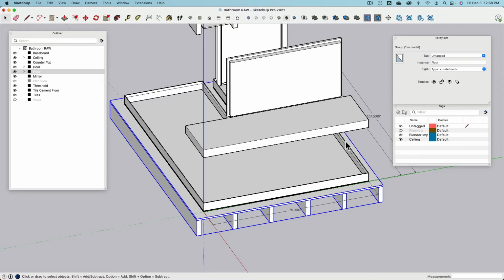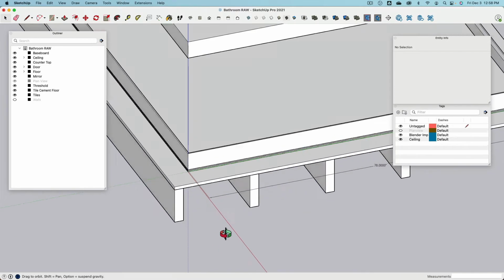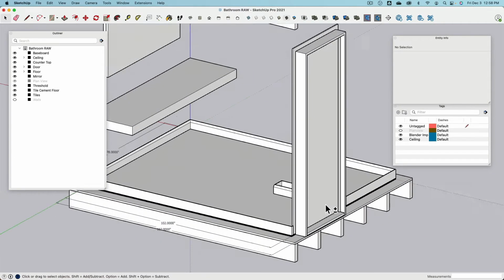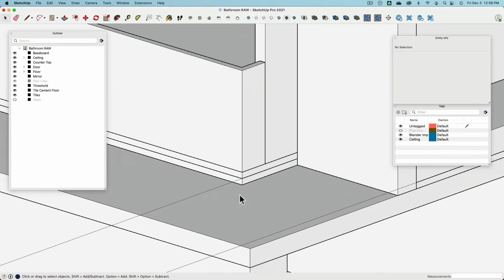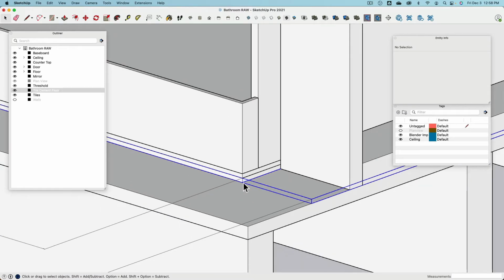Now, because this is wood, it can move, which is fine. It's a natural material. But that means if I take tiles and glue them right onto my subfloor, chances are very high that at one point it will break. The mortar might break, the tiles might crack. That's terrible. So how can we prevent this? Well, the easiest way is we need to put something stable under it.